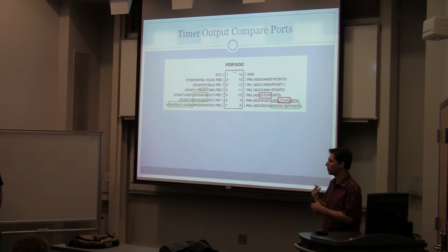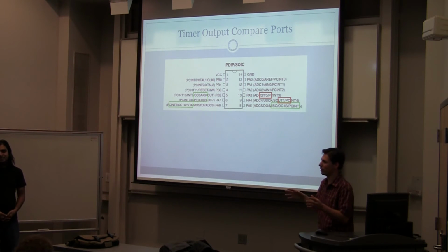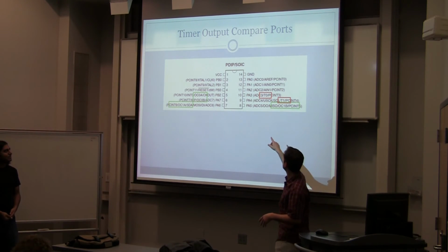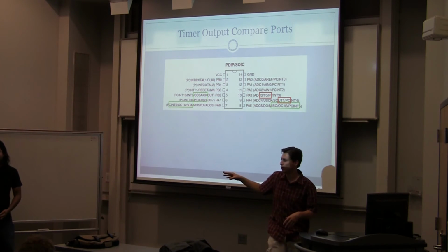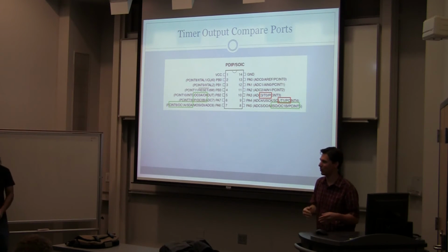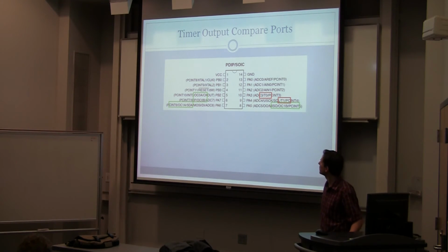So this is important if you've got a buzzer where you actually want to modify the frequency over time, because you want a high note and then a low note. You wouldn't use OC1B for the buzzer and OC1A for motor controls, because you don't want a variable frequency going into a motor; that would cause all sorts of problems. But you can use both of those channels for two different motors, though that'd probably be complicated.